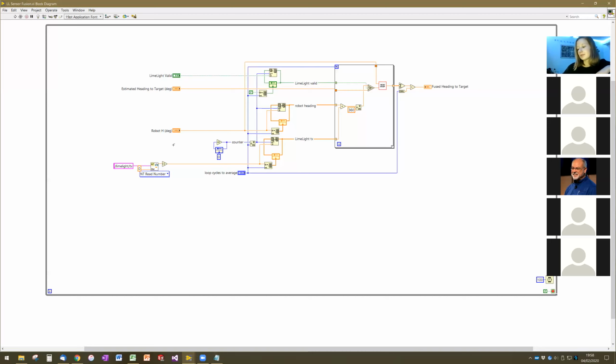And so what we end up having to do is memorize the robot's location when we measured it with the camera, and then also adjust that for the amount that the robot's rotated with the IMU. And that, again, improves our total accuracy for how we're estimating the total angle. I'll talk about the solution in a second. Does that problem make sense? Or are there any questions about that problem?